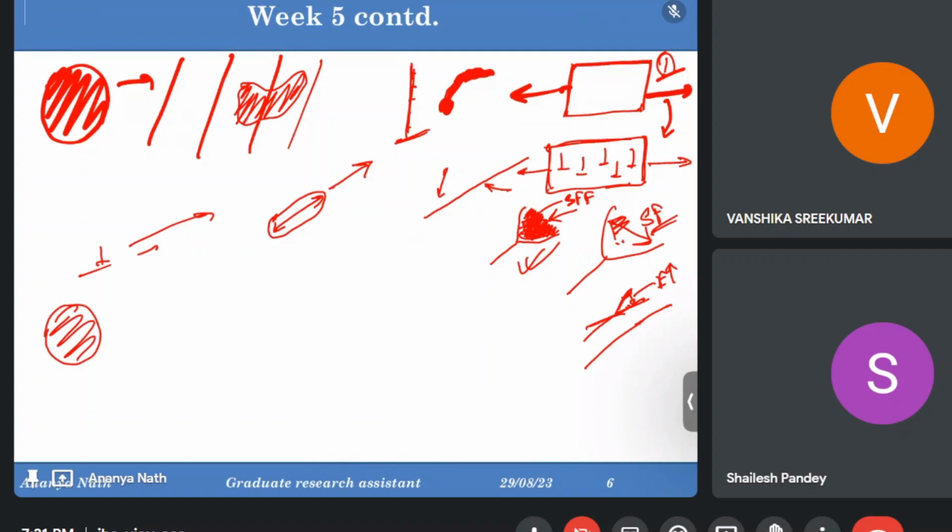We cannot define those things. So what we do is we separate out this piling up. We let the dislocations be arranged in the pile-up configuration only, and this is how we do the recovery. And recrystallization means we do certain things by which some new strain-free grains will be nucleated.